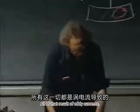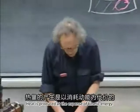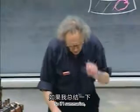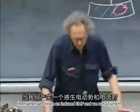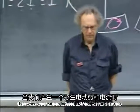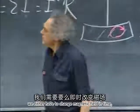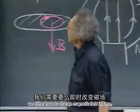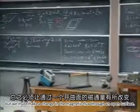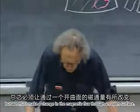All of that the result of eddy currents, all of that the result of Faraday's law. Heat is produced at the expense of kinetic energy. So if I summarize, then when we create an induced EMF and we run a current, we either have to change the magnetic field in time, or we have to change the area in time, or we have to change the angle theta, but we must make a change in the magnetic flux through an open surface.